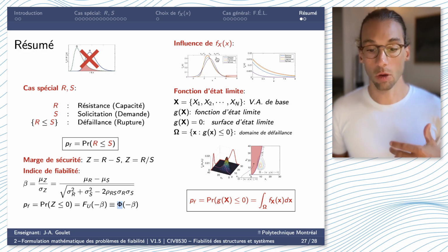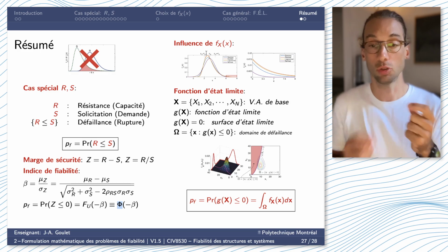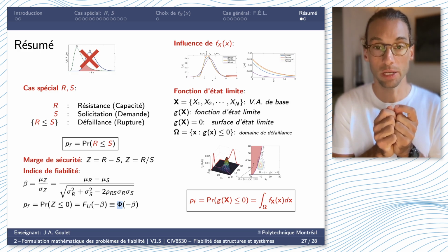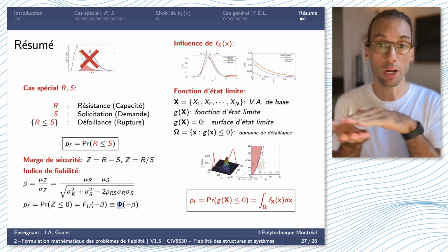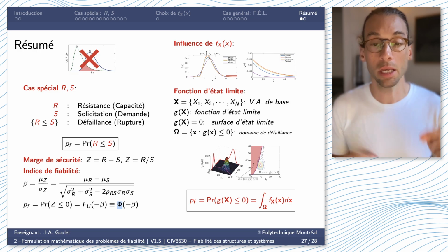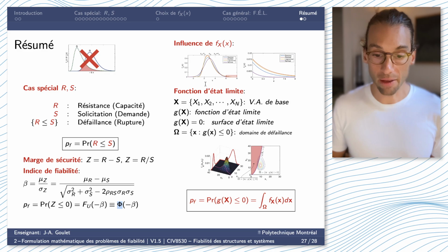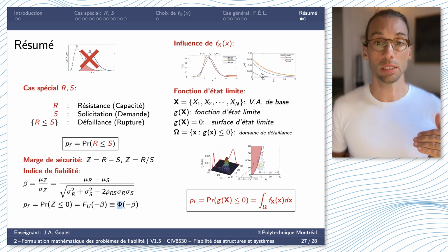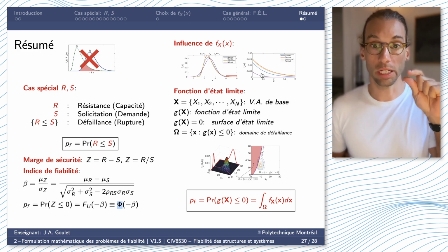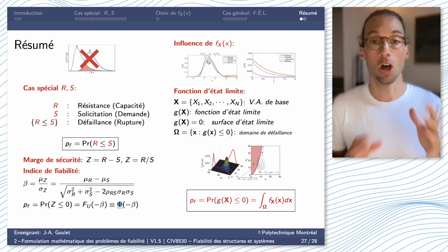We saw that it matters to choose the correct probability density function to model your quantity of interest because we're looking at what's going on far out in the tail. In the context of structural reliability, we're looking at small probabilities of failure occurring far out in the tail, where there can be very large discrepancies between the probability density function values, even if the core content around the mean all looks the same.